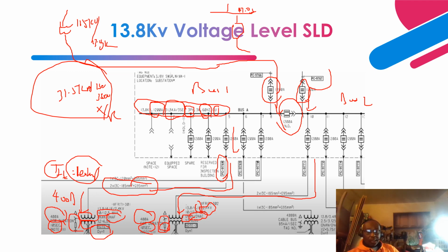Okay. So similarly, it's another feed that goes to another step down transformer, right? But this time we are stepping it down from 13.8 kV to 480 volts, right? We are trying to achieve a motor control center at 480 volts. Okay, so this is how we are able to synthesize different voltage levels at different medium voltage levels, 13.8 kV to 4.16 kV to 2.4 kV. And as a matter of fact, we can even go from 13.8 kV to 6.9 kV.